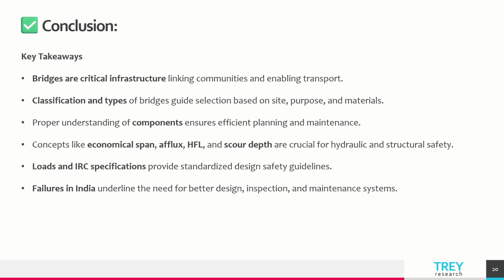Concepts like economical span, afflux, HFL, and scour depth are crucial for hydraulic and structural safety. Then loads and IRC specifications provide standardized design safety guidelines. And the last point is that failures in India underline the need for better design, inspection and maintenance systems.